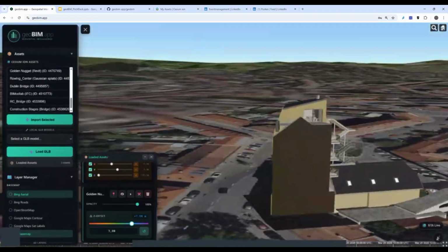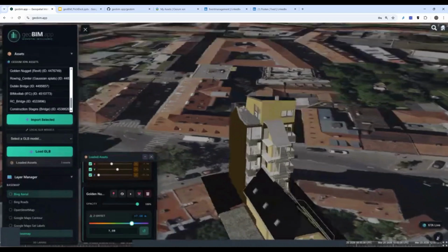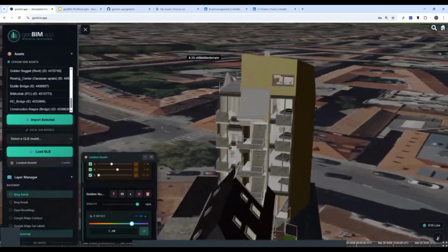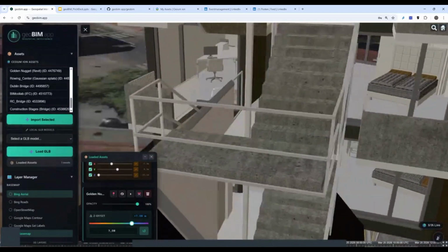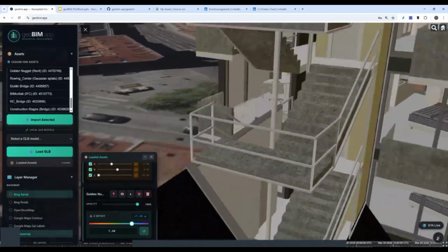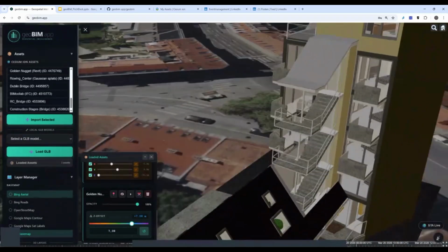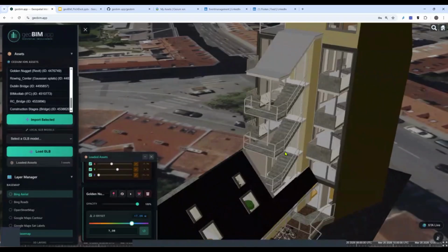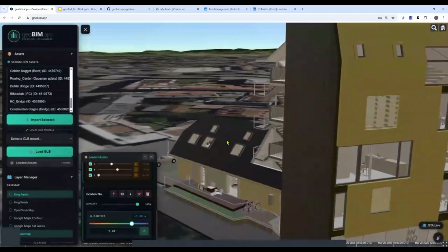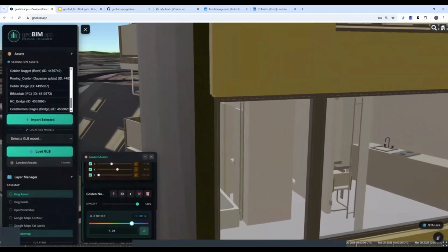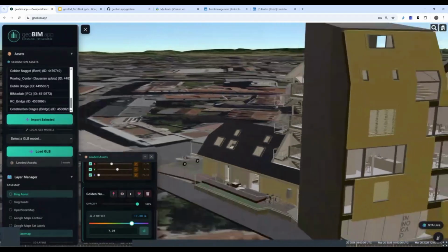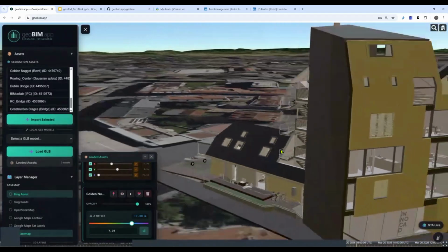So what you realize is this is coming directly from the Revit importer. There's a plugin in Revit, and it will take all the material textures as well, which makes it, of course, a little bit neater than the IFC files, which would potentially be able to transport material information as well, but it's not getting parsed usually. And you see this is a quite high fidelity model coming out of Revit. The same procedure here.